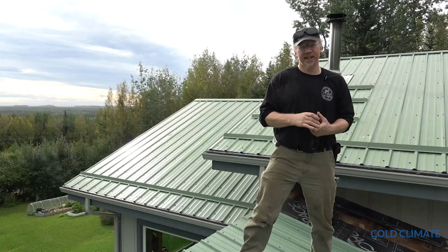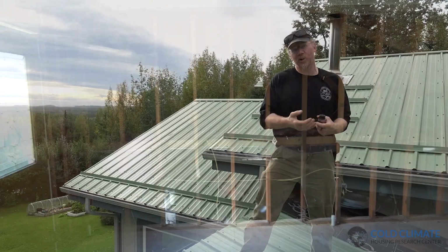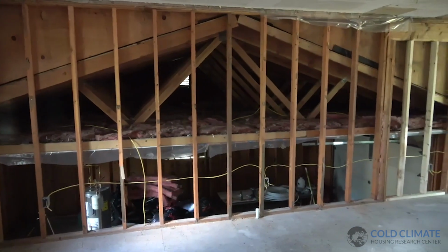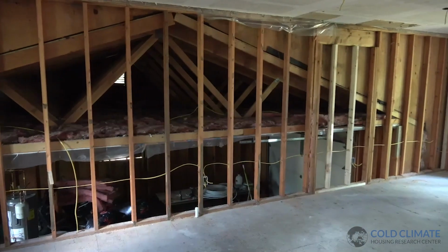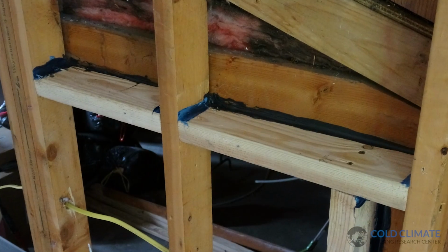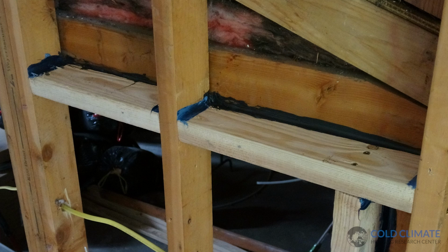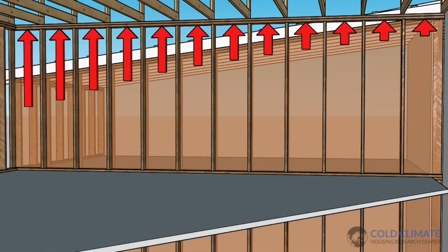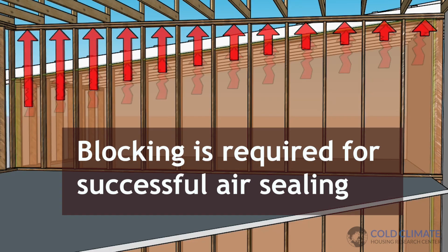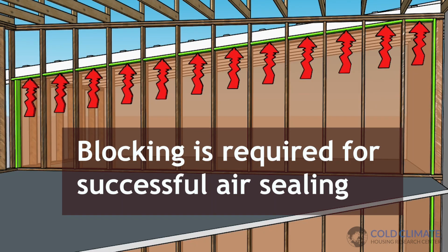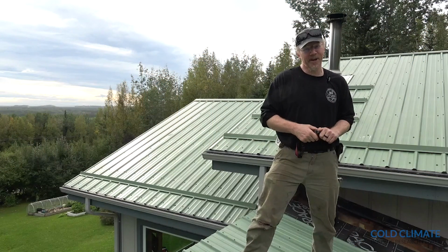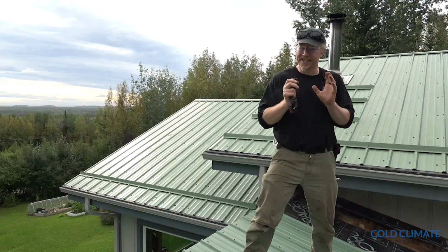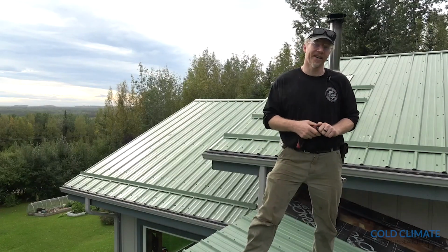During remodels, it's more trouble, but you will have to open up the wall and you will have to identify where's your pressure boundary and where does your blocking need to go. There's no way around it. If you think you can rely on air sealing, it will never work, and you will end up with a case like this where we were the 3rd attempt at fixing this roof. It's far better to address this, to identify it and address it at the start.